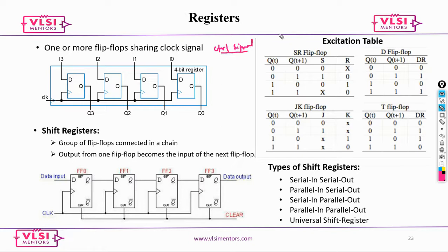Say you design a system with a 4-bit input A, two control signals S1 and S0, and an output Q. Now say S1, S0 is 0 0: just a pure register, a parallel load kind of thing. 0 and 1: now shift left.